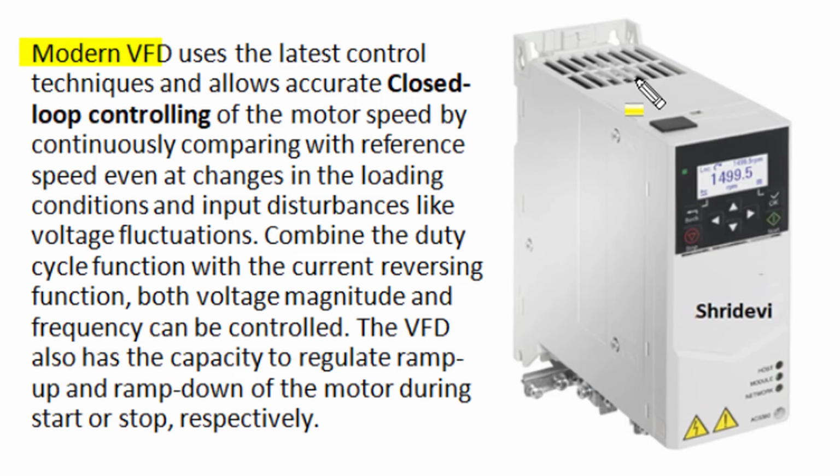Modern variable frequency drives also have the capability to regulate ramp up of voltage for soft start, and they can also provide ramp down of supply voltage for soft stop of motors if required. And some VFDs also have a regenerative braking facility, and during stop action they can regenerate inertial energy back to the supply side.